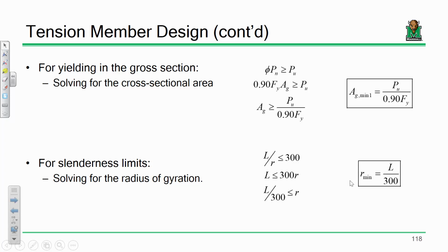Well, I could probably say, if it's going to be a wide flange, it's probably going to be A992 steel, or if it's an angle, it's going to be grade 36 or whatnot. So I can probably determine the material properties really easily, just based on the fact that I know I'm going to use a wide flange, or a channel, or an angle. That's pretty simple. In design mode, that's what I need to know, so why don't I just solve?